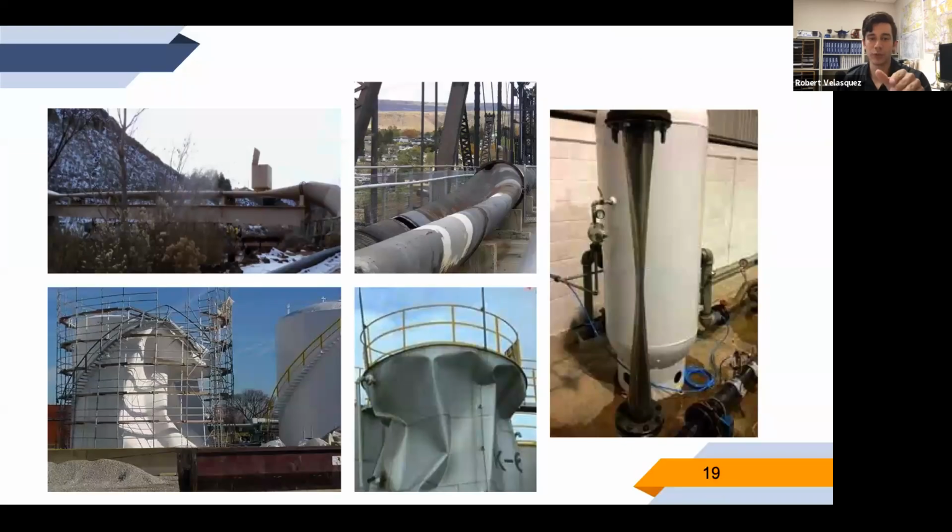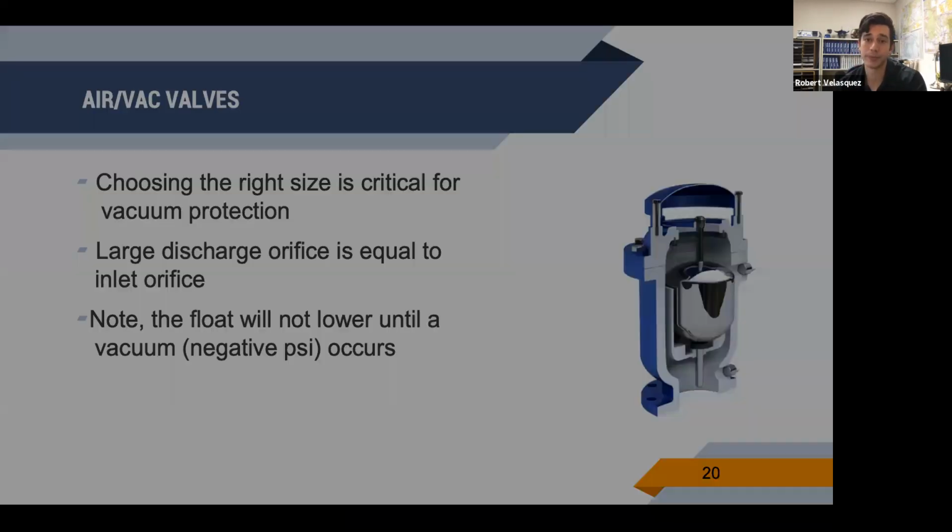Another thing that I did mention as well, pump failure is another common cause of surges. Also line breaks are a common cause of surge. If I've got a reservoir on top of a hill, and a pipeline that's running steeply down the hill, and at the bottom of that hill the line breaks or a valve breaks open or something, and water rushes out, I've got gravity pushing that water down, and something needs to take its place. If the water moves too fast, then you can get negative pressures. And so that's where an air vacuum valve would help put in air, so at least you have something and you don't have negative pressure.